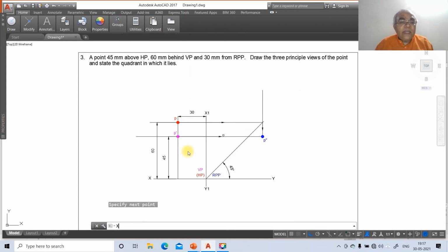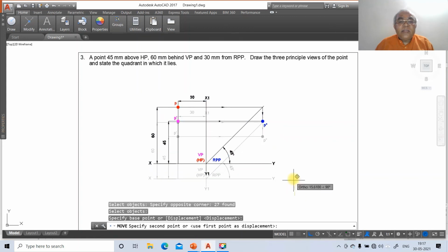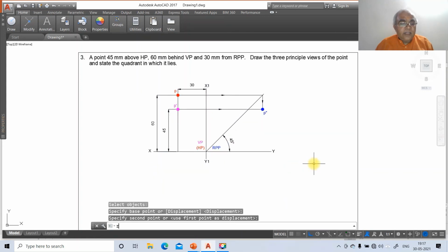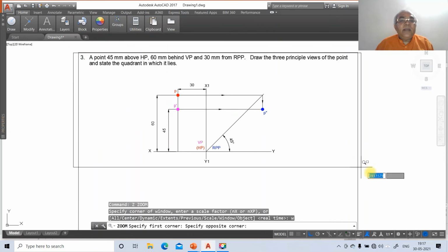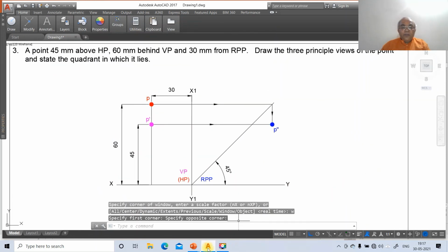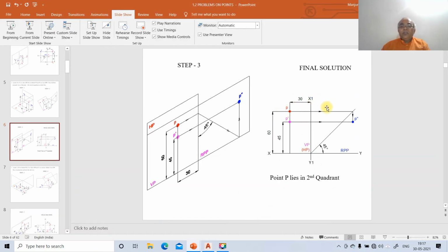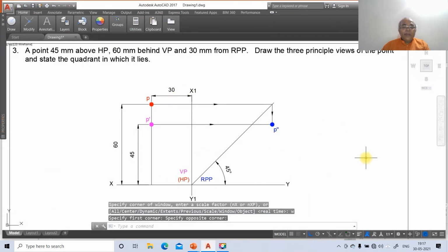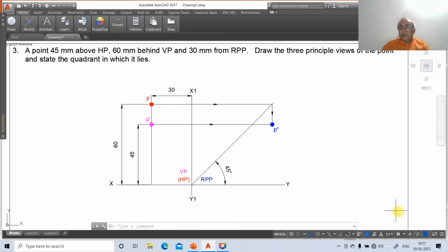So then go to explode X, select this line and you select this line and then go to erase, erase this and erase this. Then go to move, select this entire drawing and take it nearer to the point, and then we are going to check finally how this output is going to be with your drawing. So this is matching with this particular drawing, and now this is how you will be able to get the drawing completed on this AutoCAD screen.